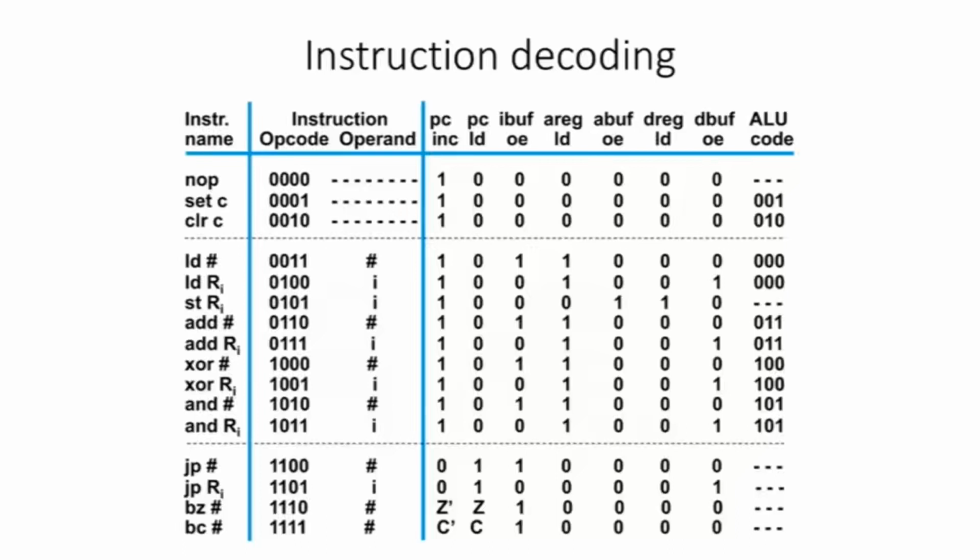And then you just go over all the control signals in your processor and you say, okay, when we do this operation, then this control signal should be 1 or 0. And then again, this is basically a truth table, and you can synthesize a logic circuit from this. Or you can let your computer synthesize a logic circuit from this. And that's basically all there is to it.